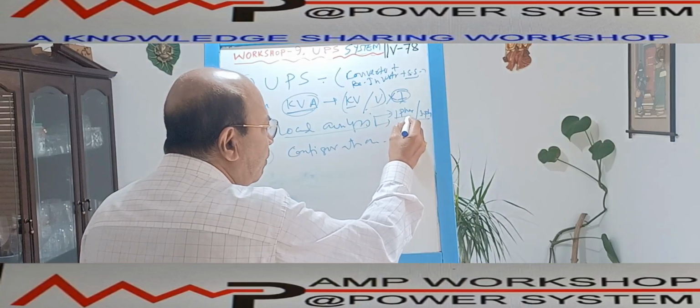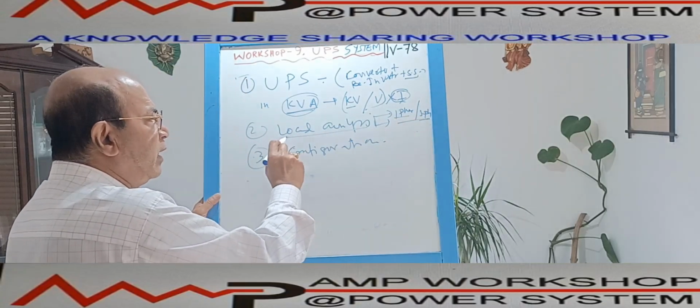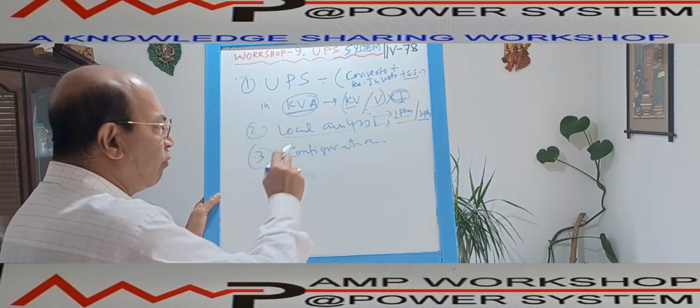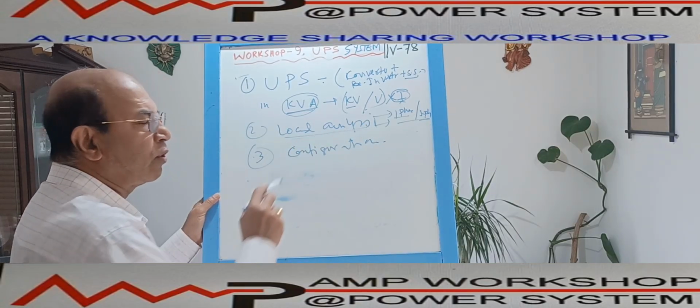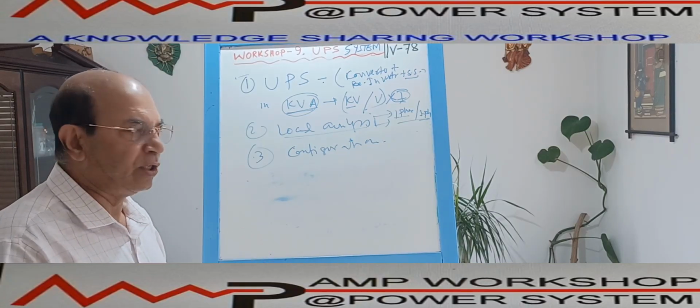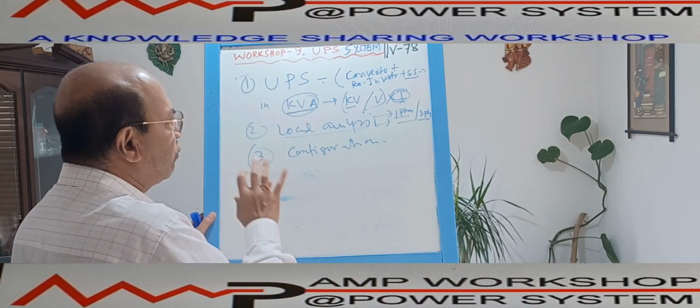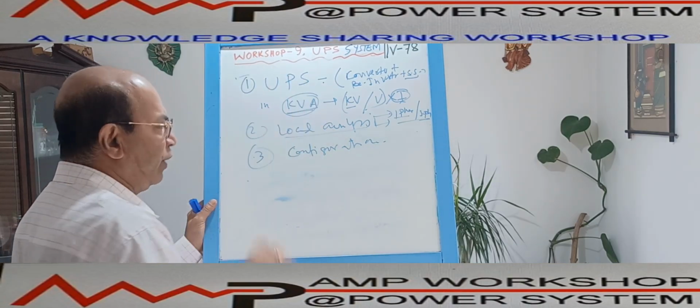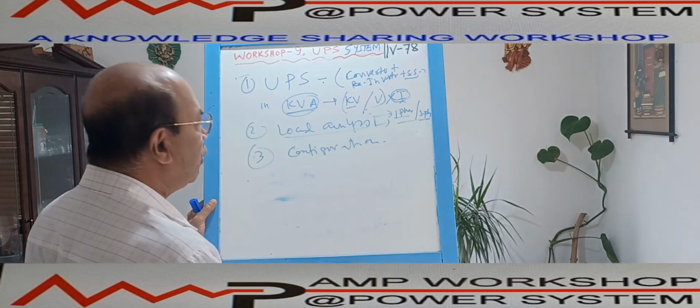Whether the load is single phase or three phase, we also have to identify that during the load analysis. Then once the load analysis is done, we have to look into the configuration. Based on the configuration, UPS sizing may change. So these are the three major parts we need to follow when deciding the UPS. Now we are discussing the load analysis.